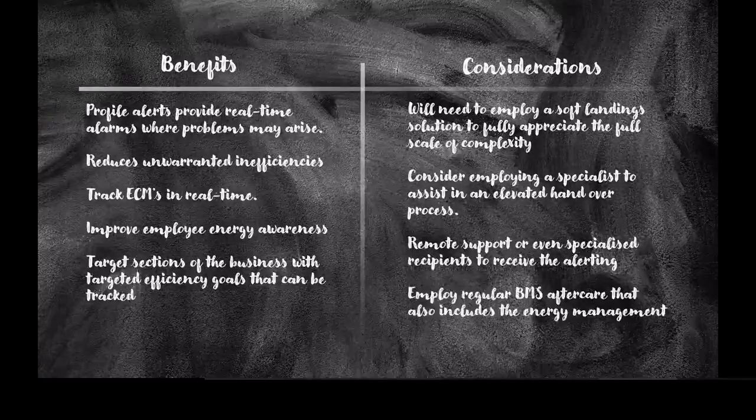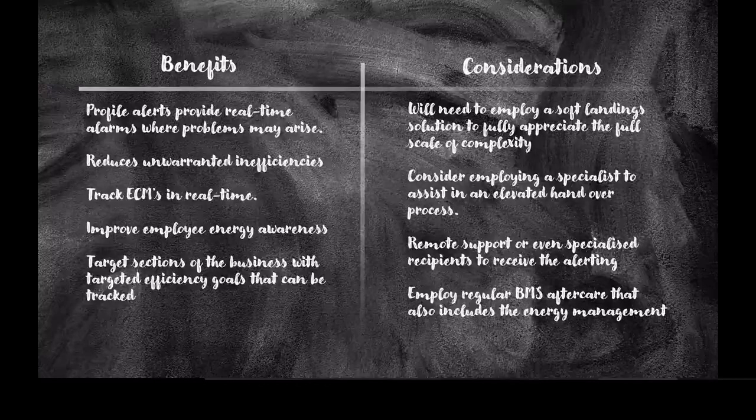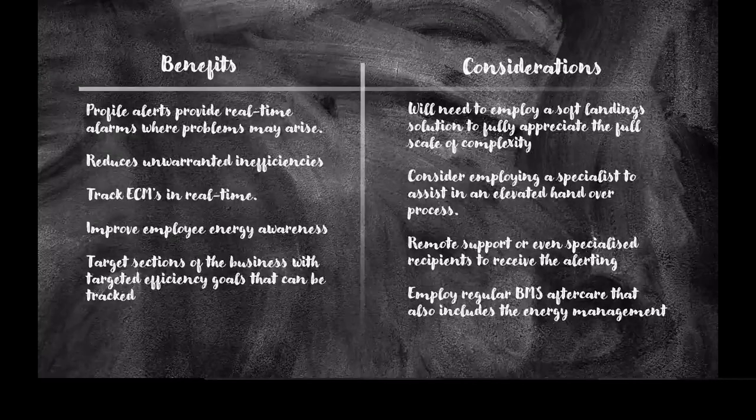And employ regular BMS aftercare. That also includes the energy management. So not just doing your traditional point-to-point checks and raising actuators and whatnot, but actually looking at energy, looking at ways in which the energy can drift and how we can be on top of that.